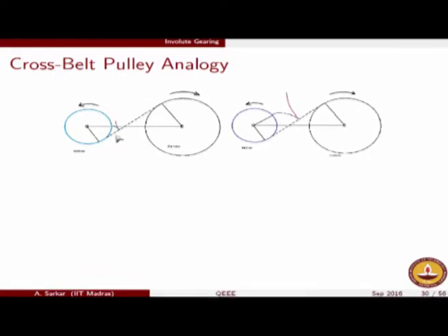That is not difficult to visualize. But now, if we think that we are sitting not on the inertial frame, but on this blue pulley, then what happens? With respect to the blue pulley, we will see that the string is getting unwound, as the blue pulley is fixed, right. So, definitely we understand that the belt is getting unwound from the blue pulley as the motion is taking place. That by definition should generate an involute. As this belt is getting unwound from the blue pulley, the driven pulley, it is going to generate a curve of the form that is shown. That is definitely an involute.